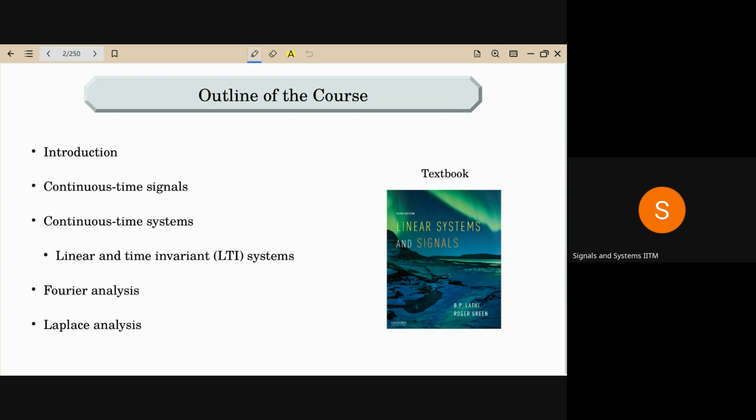And after machine learning, we have moved off from wavelets. Now we are constructing our own generic orthogonal basis. If we pick images, we have different kinds of orthogonal bases there. For audio, we have a different kind of orthogonal basis. Depending upon what your signal is, we can construct our own basis, which is very useful for analysis of that particular signal alone. If you want to take an audio signal and remove noise from it, the noise will have a different representation, a different spectrum, in that particular basis. So it becomes easier to filter out noise.